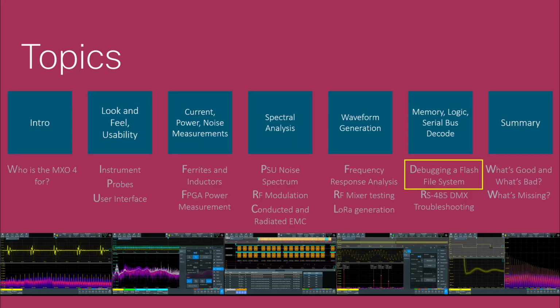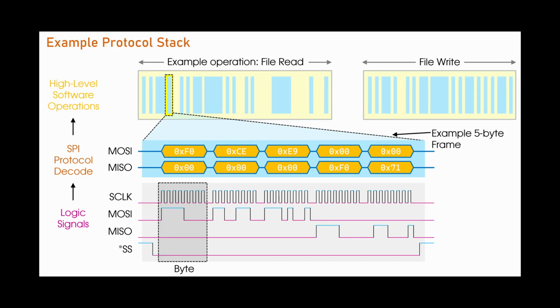I decided to spend some time looking at onboard and offboard serial protocols troubleshooting. A neat thing about the MXO is that its entire memory is available for logic capture. In my case, I had the additional memory license installed, which provides a total of 1600 million samples. My main challenge when working with serial protocols is that since protocols can be layered, it is tricky to traverse up and down the stack based on the problem being debugged.